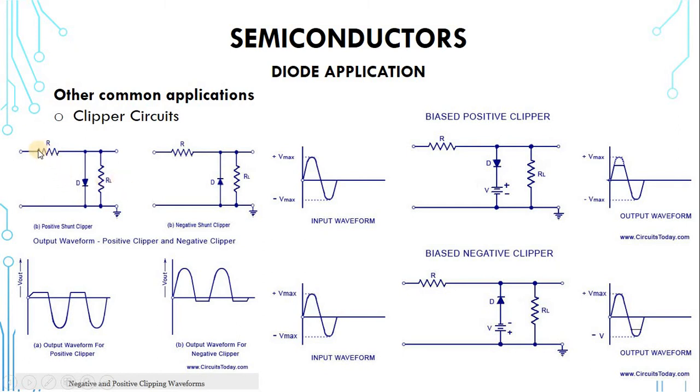But when this resistor is not there and the diode short circuits, it also short circuits the power supply. And once there's a short circuit of the power supply, there could be maximum current flowing. There could be a blast. It could cause fire. So we don't want that to happen. You will never want to short circuit the power supply, especially when the voltage is high. There's going to be trouble. So this is there to prevent the source from being short circuited.